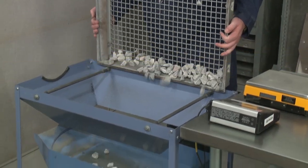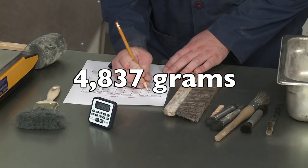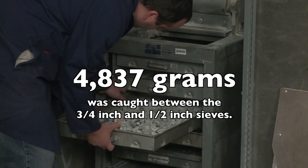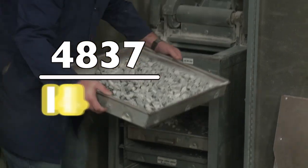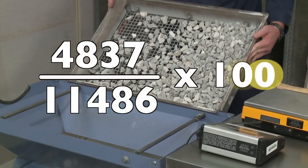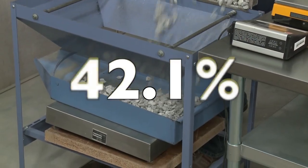Again, using the half-inch sieve from our example worksheet, 4,837 grams of material was caught between the 3/4 inch and the half-inch sieves. 4,837 divided by 11,486 times 100 equals 42.1%.